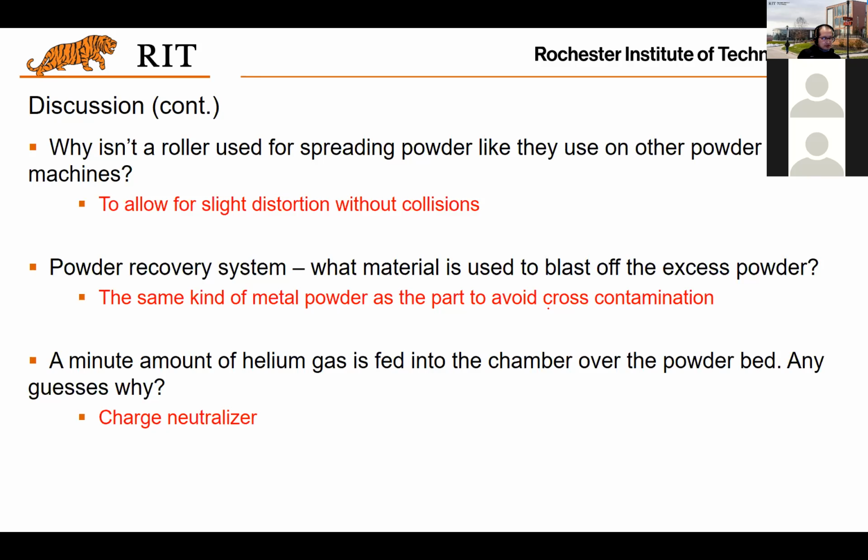And the last thing is a minute amount of helium gas is fed into the chamber over the powder bed. And why do you use such a gas? Basically, that will neutralize the charge, because you are talking about some electrons during the printing process, right? Definitely you want to neutralize them.